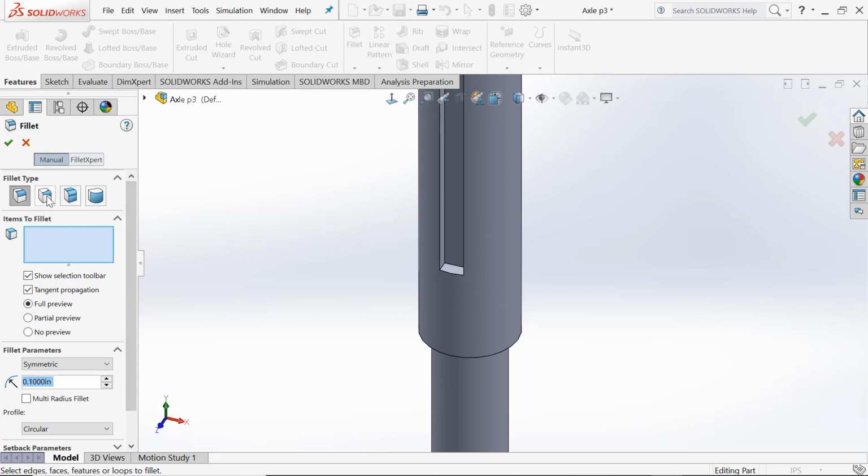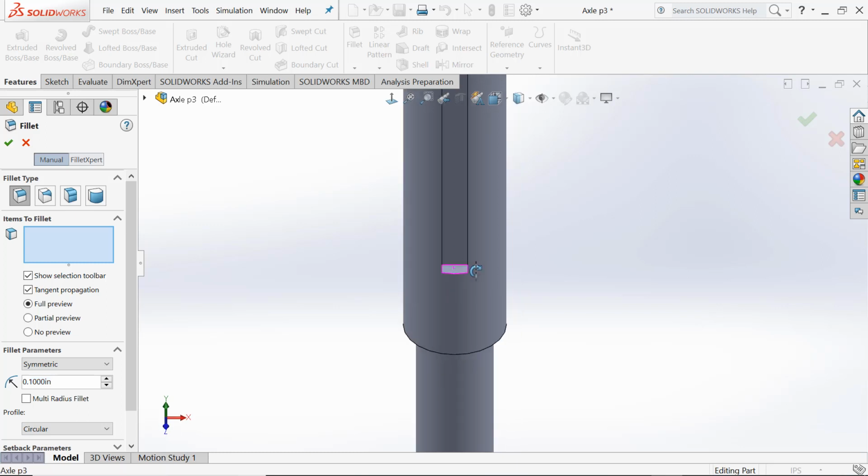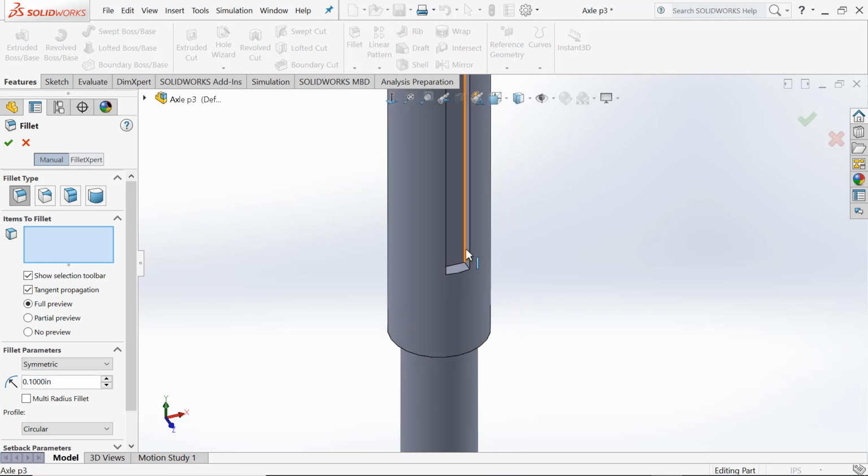And as I pointed out, there are actually 4 kinds of fillet possible. We usually use just the first one, which is a constant radius fillet, or we use the last one, which is a full round fillet, which is what we want in this case. A full round fillet figures out what radius of curvature would be able to start off at this surface, just touch that surface, and then continue curving on around to touch this surface. It's tangent to all 3 of those surfaces. And SolidWorks figures out what dimension that needs to be, so you don't have to worry about that.